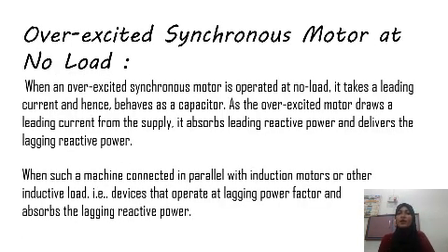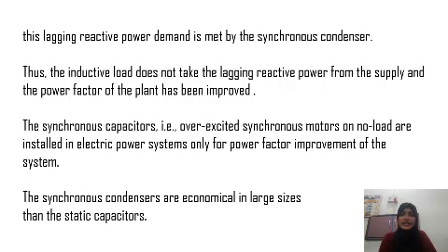When an over-excited synchronous motor is operated at no load, it takes a leading current and hence behaves as a capacitor. As the over-excited motor draws a leading current from the supply, it absorbs leading reactive power and delivers the lagging reactive power. When such a machine is connected in parallel with an induction motor or another inductive load, that is a device that operates at a lagging power factor and absorbs the lagging reactive power, this lagging reactive power demand is met by the synchronous condenser.